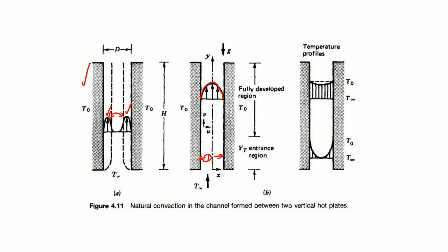Similarly, you can see what happens when you have the temperature profile, distinct versus not so distinct. In these cases also, as we know, the boundary layer takes a little bit of time to develop, the same as in pipe flow or any other flow. So, there must be some kind of an entrance length before these two layers actually merge with each other. There should be something like this, and that merging length is given by this parameter which we call yt. So, yt is the parameter which governs this.